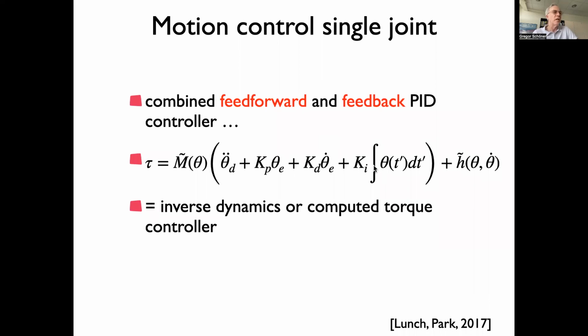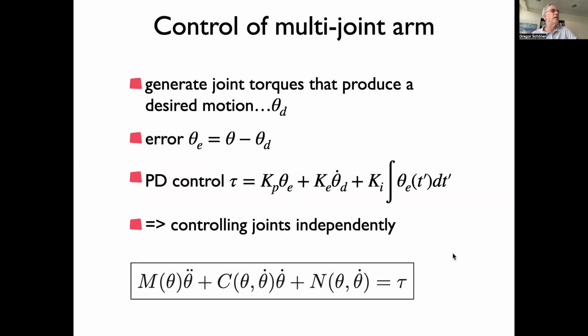Right? This is actually called inverse dynamics, even though it looks like it's a forward model. The inverse dynamics consists of inserting an active torque that is proportional to the kind of terms that you have in the equation so that they cancel. What's called a computed torque controller. And that is something that is being done; there are robot arms that really realize that kind of system.